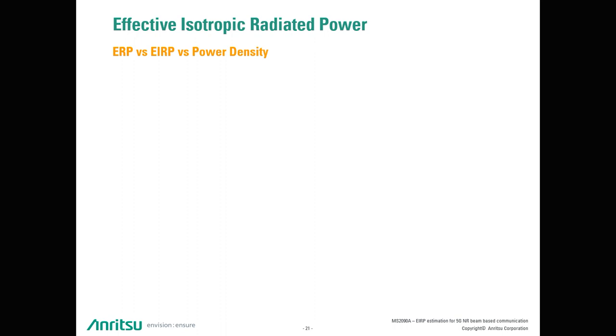In the previous section, we have seen some examples where the maximum allowed EIRP is given as an absolute power related to milliwatt, a dBm figure. It can also be defined as a radiation flux density in watt per square meter, because the RF radiation hazard safety limits are based on exposition rates and power flux density. With the knowledge of some fundamentals, it is relatively easy to convert one figure into the other.